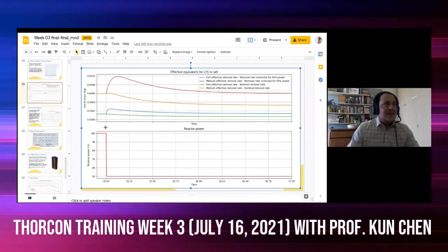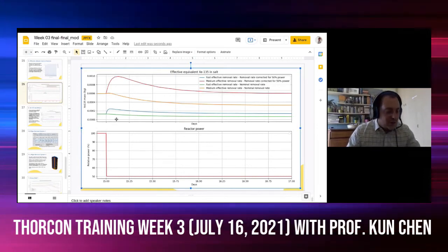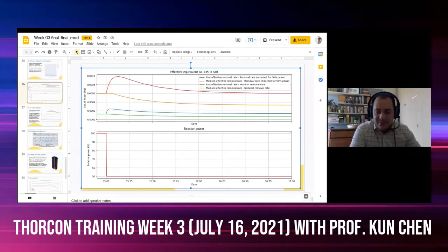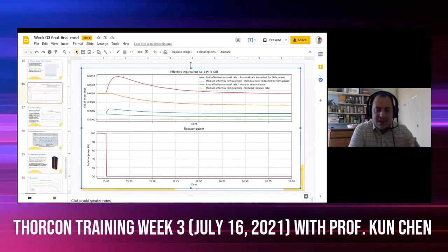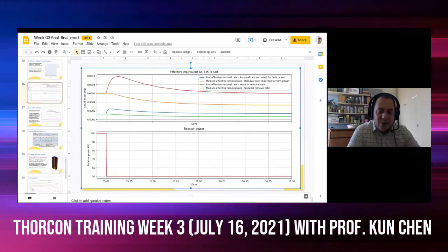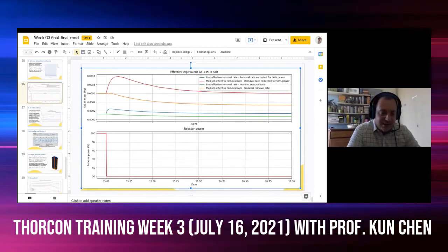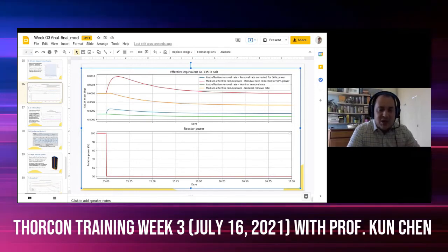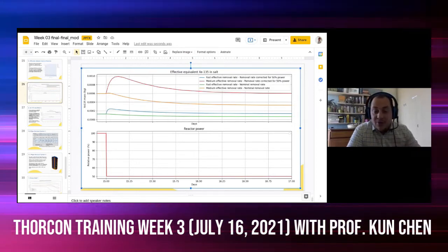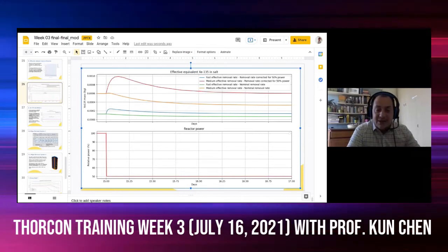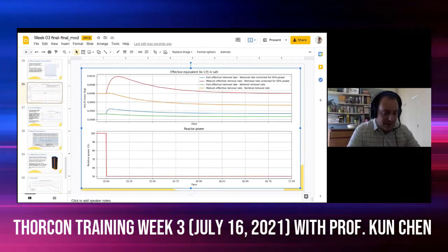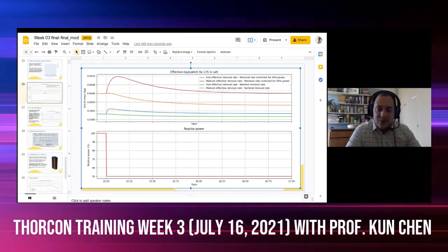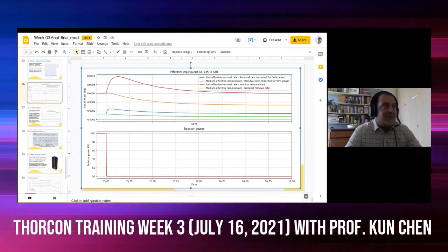In this case, the xenon in a solid fuel reactor would reach a well-known level that just depends on the amount of iodine-135 that is produced as fission fragment and fission product decay chain, the amount of xenon-135 that is destroyed by neutron capture, and the amount of xenon-135 that naturally decays.